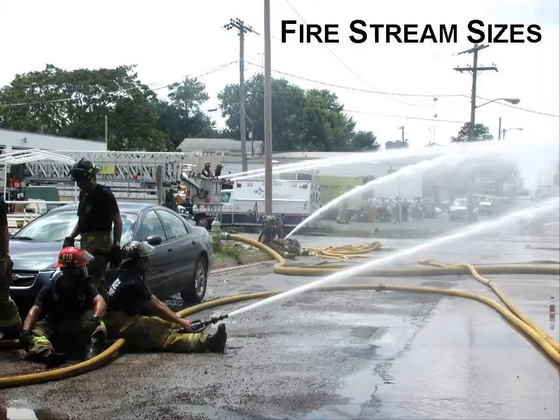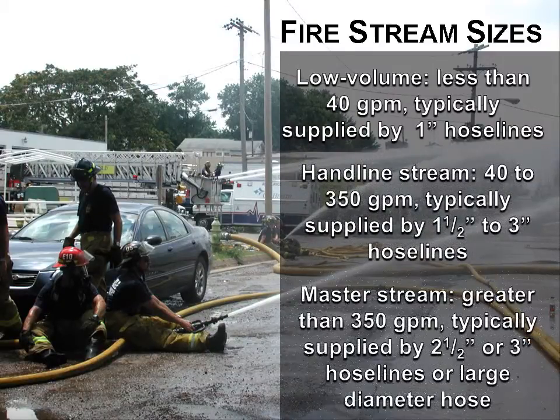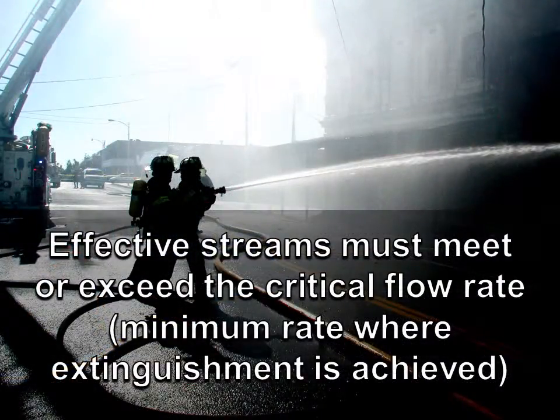Fire stream sizes: low volume, less than 40 gallons per minute, typically supplied by a 1-inch line, which is commonly your forestry line or booster line. Your handline streams are 40 to 350 gallons per minute, typically supplied by 1.5 to 3-inch line. Master streams are greater than 350 gallons per minute, typically supplied by 2.5 or 3-inch hose line, or they can be supplied by a large diameter hose such as a 4 or 5. The amount of water discharged is determined by the nozzle design and the water pressure at the nozzle.